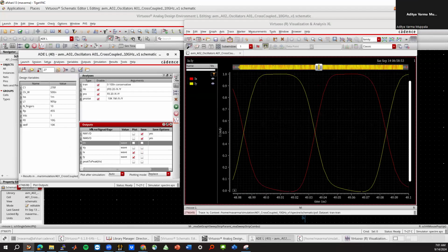So one thing we can do is to see, if I increase the size, does this change? Things like that. You can play with that and see. Essentially, you want to make sure that you don't drive it beyond this. Otherwise, you'll start getting worse noise performance, right? Because we saw that one way to think about that is that the noise figure minimum was at lambda, was when the width was 10, and we are only at 5 right now. Yeah, so you can try different sizes and things like that and see if this gets any better. But essentially, we are driving it to pretty much a square wave. I don't think it'll improve much.